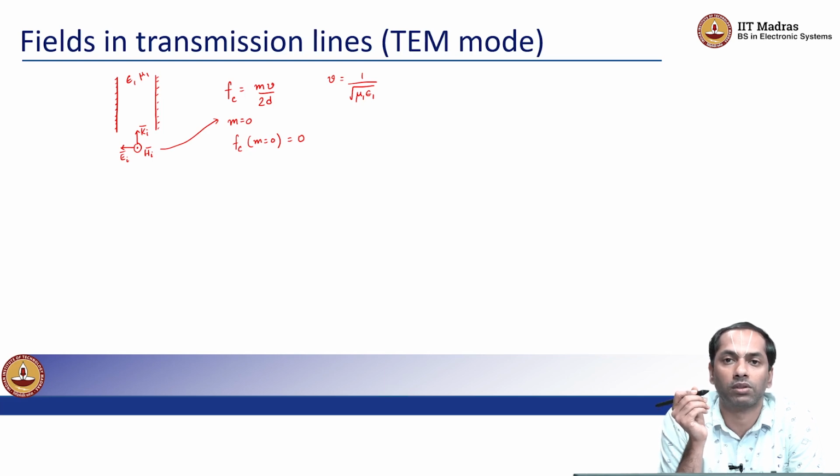So when we use coaxial cables, the way these electromagnetic fields are propagating from one end to the other end of this cable is mostly dominated by the TEM mode, because you would most likely use these cables at very low frequency applications, say for example kilohertz or megahertz, to which this is rated. So this coaxial cable is rated to operate in the megahertz range.